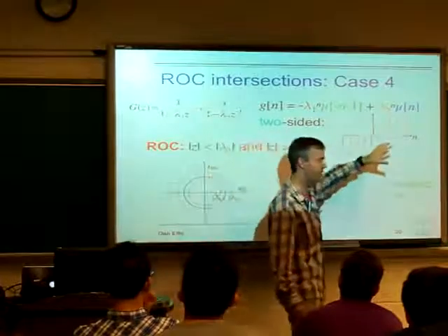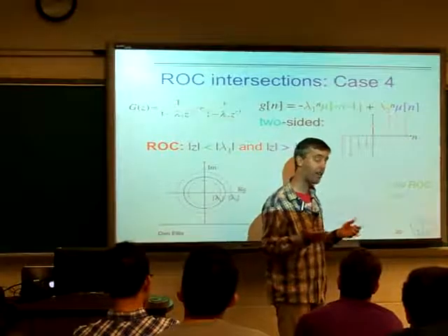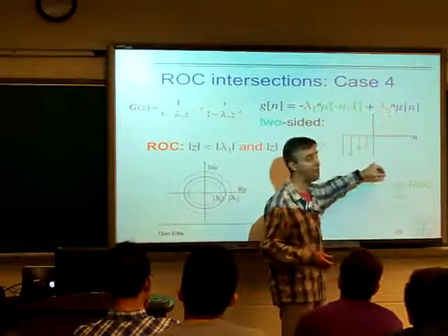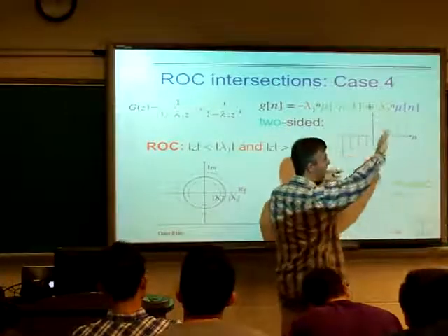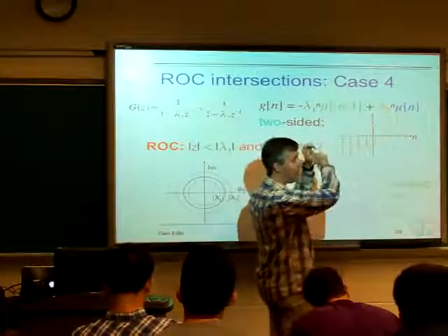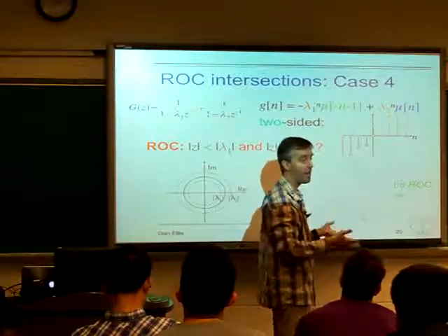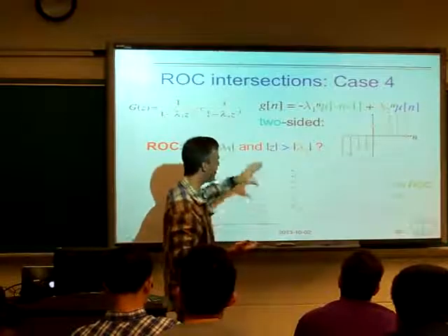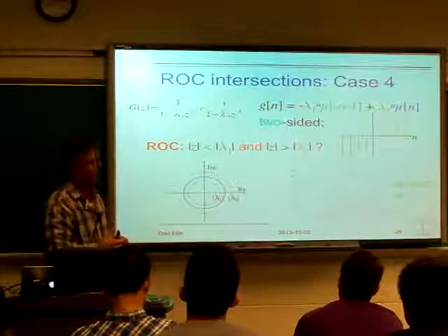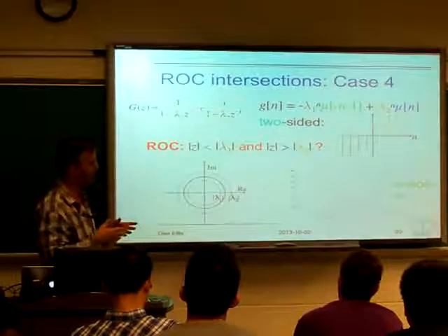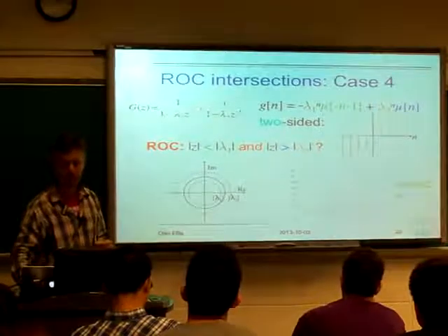And so we said that the z-transform can describe sequences that we are unable to describe with the Fourier transform. But here's a sequence where we're unable to describe it with a z-transform because there's no value of z for which it converges. So this is exploding in multiple ways. What this says is there's no value of r to the n times g of n which is convergent, and so we basically can't handle it with the z-transform. But you see how it emerged out of the way we're thinking about it. It's just a little investigation of how this region of convergence and sidedness thing works out.